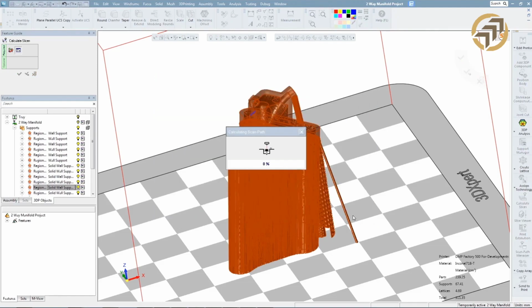However, for customers who are willing and have the capacity to define their own parameters, 3D Expert offers an unprecedented open interface to control each and every parameter of the slicing and the hatching. There is much to be told about build parameters, but unfortunately, we don't have time to go into it. Two other issues I would like to touch on quickly are 3D zoning and offloading calculation. 3D zoning is a patent-pending technology included with 3D Expert.